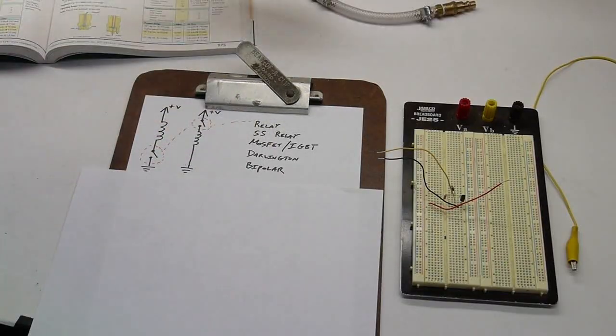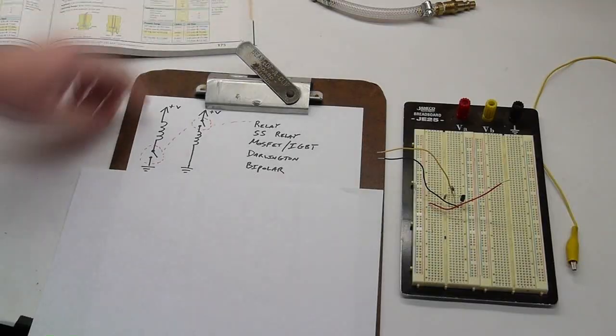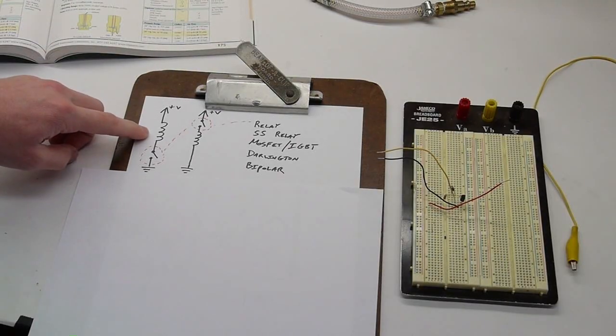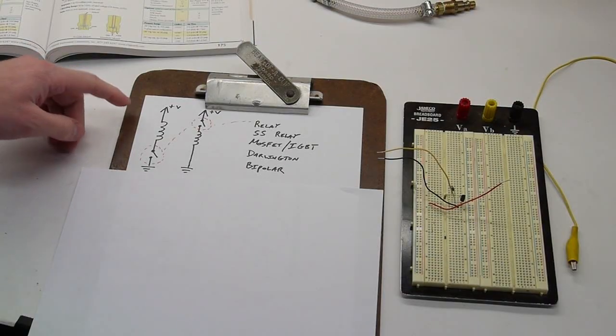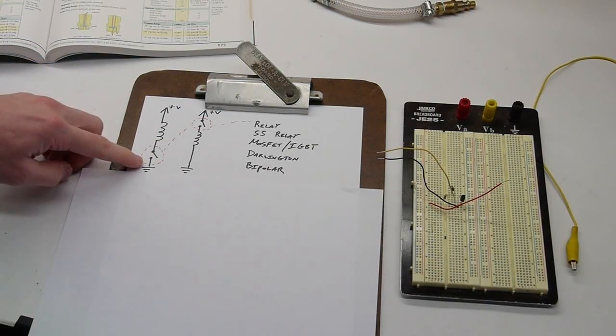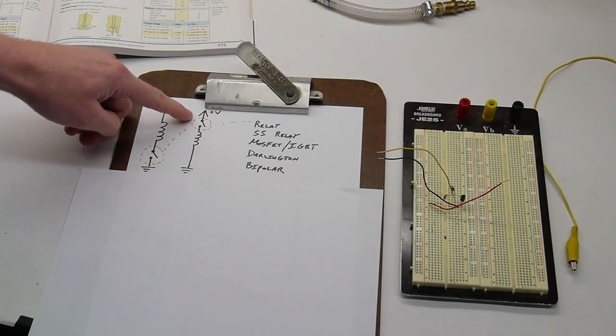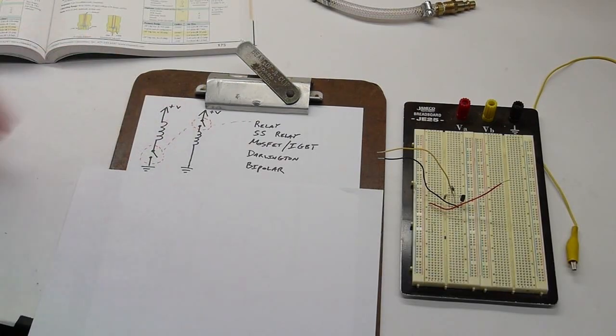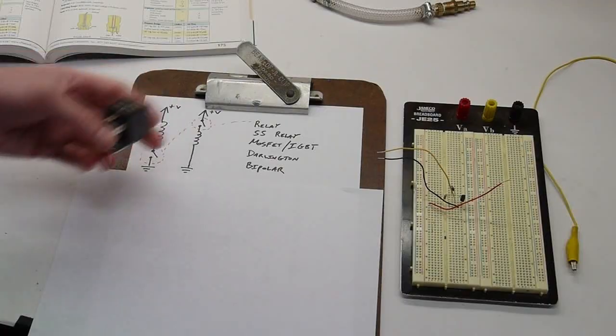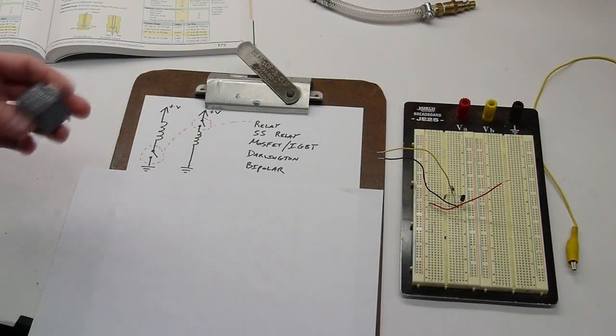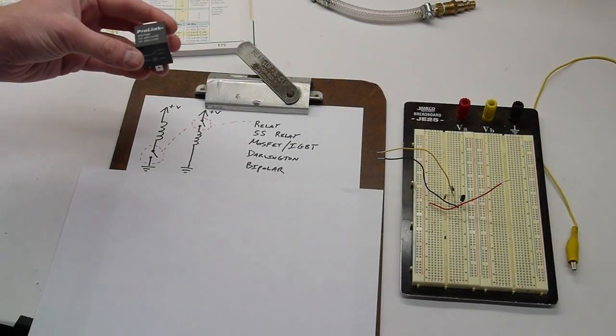You just put power on it and it opens. Pretty simple. So I just drew it in this diagram as a coil, which is a good way to represent it. It's like an iron core coil. So to turn the thing on and off, we could either put a switch between the coil and ground or between the coil and our voltage source. It doesn't really make any difference to the coil, but it will make a difference to us later if we choose a switching component. So I listed off a few of them, and I'll describe why I did or didn't pick them for this project.